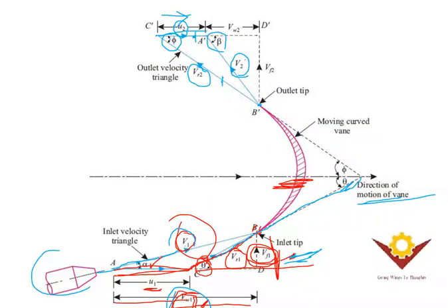And now here we have three cases with respect to this beta, and if this beta is more than 90 degrees, it will place here. If it is equal to 90 degrees, you are going to get the V2 here. Okay, and now if beta is less than 90 degrees, then you are going to get the triangle like this.